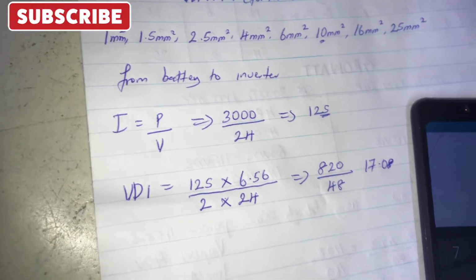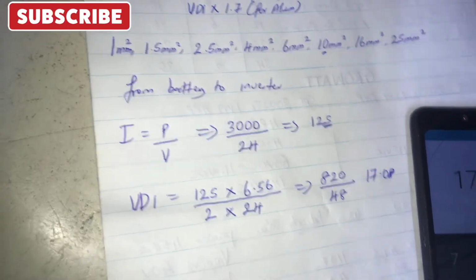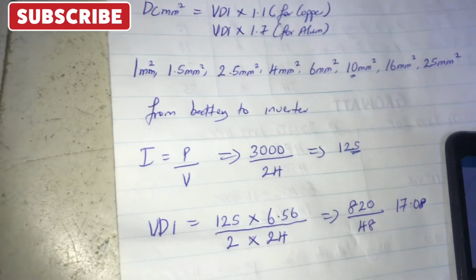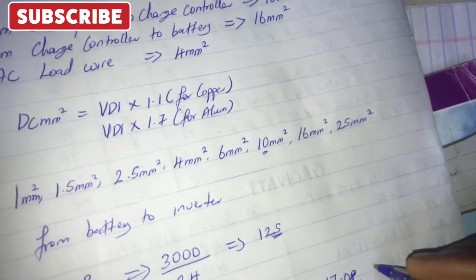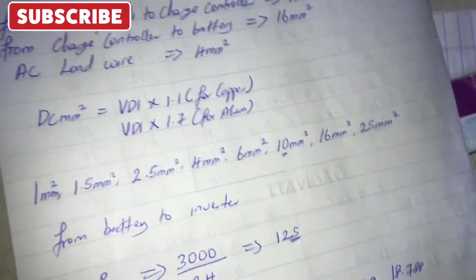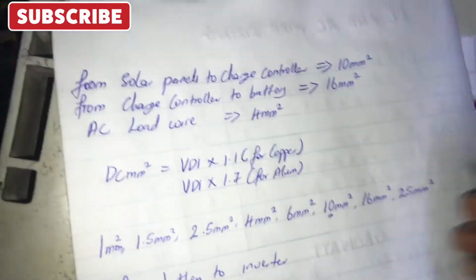We have 17.08 multiplied by 1.1, because we are using a copper wire, not aluminium. So we have 18.788. So the nearest whole number here for 18.788 is 25 mm.